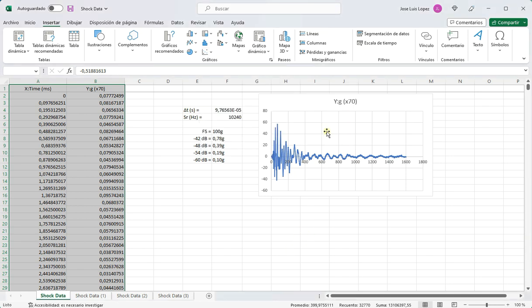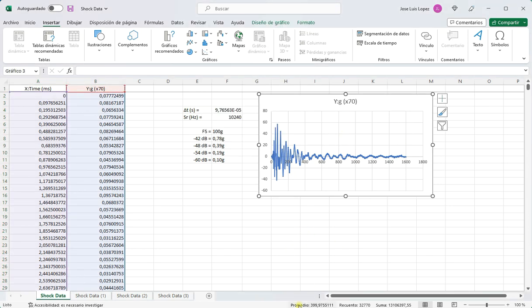The shock duration T-e is defined as the duration from the zero crossing for the first measurement acceleration above the instrumentation noise floor until the perceived termination of the shock. Therefore, we analyze the first region of the signal looking for what could be considered the instrumentation noise floor and the last region of the pulse.